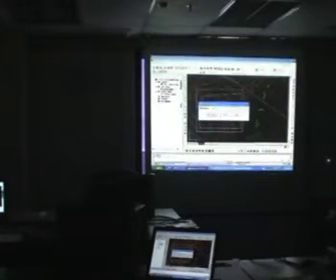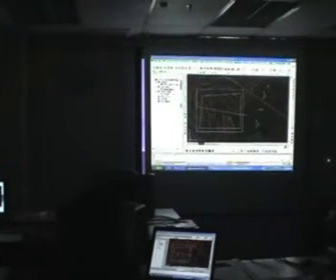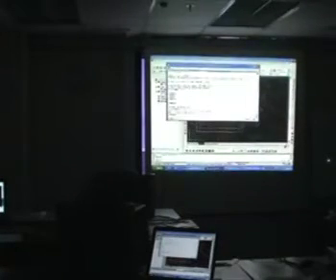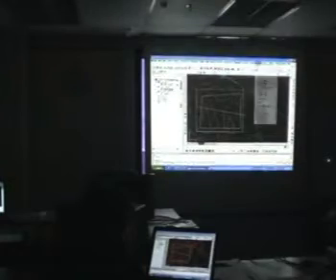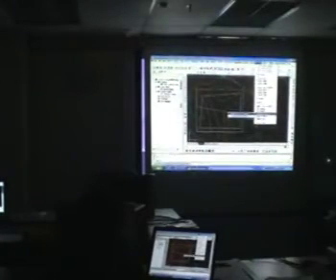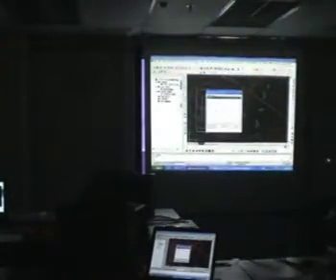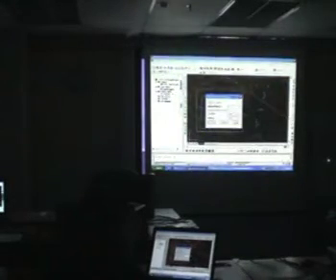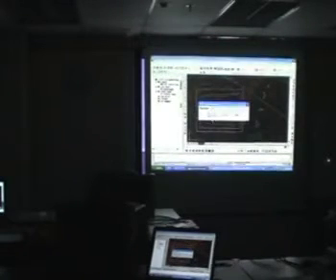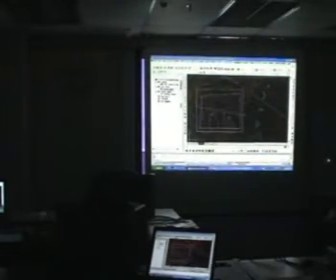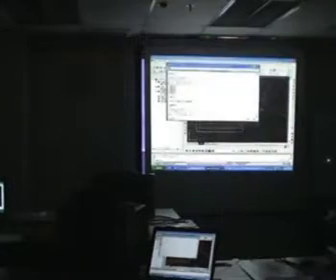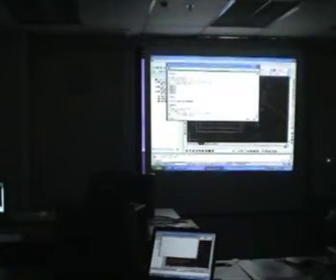I'm just going to call this grid. And the volume coefficients appear at the bottom. So I'm going to open up the history to show you. This is our cut volume, our fill volume, and our net volume. This is for the platform. For the second method, it's almost the same. You just pick calculate total site volume. Pick the site, and again, you can specify your fill factor. I'm going to put it the same as just now, at 1.2. Again, I'll call up the history. You can see our cut volume, our fill volume, and our net volume.